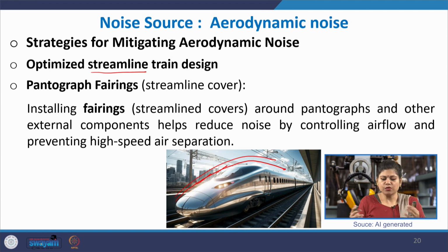In the same way, because we not just have the body, we also have the pantograph. The pantograph can create aerodynamic noise, so we can have some streamlined cover over this pantograph, fairings, and this can also bring down the noise level.